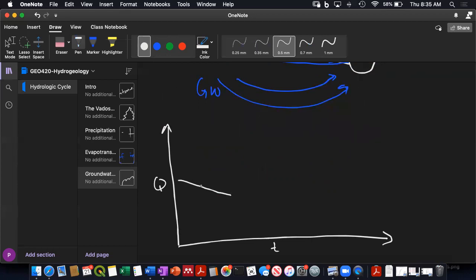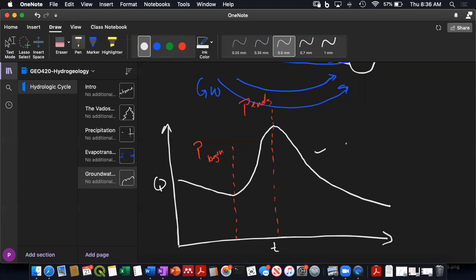During a storm event, so before the storm, we're draining our watershed, our discharge would generally decrease. And then we get a storm event, and that will increase the discharge. It'll peak. So this right here is sort of the time that the precip begins. And then the precip ends, and that'll be pretty close to our peak discharge. And then after that, the stream will gradually recess. And by recess, we mean the stream discharge decreases. All right, so in between precip events, we have recession periods.